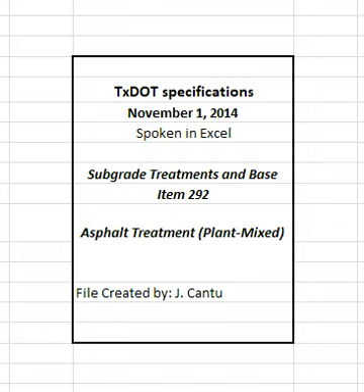2.3 Asphalt material. Furnish PG 64-22 asphalt binder that meets requirements of item 300, asphalts, oils and emulsions. When more than 30% wrap is allowed and used, ensure that the new binder and recovered binder from the wrap, when blended proportionally, meet the PG 64-22 requirements.